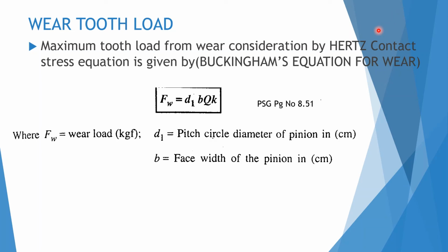Due to the contact between the two teeth of the mating gears, contact stresses are developed between the two teeth. So this causes wear on the tooth surfaces. So it is important to find out the wear tooth load before designing a gear tooth, and the wear tooth load can be calculated by using this equation,